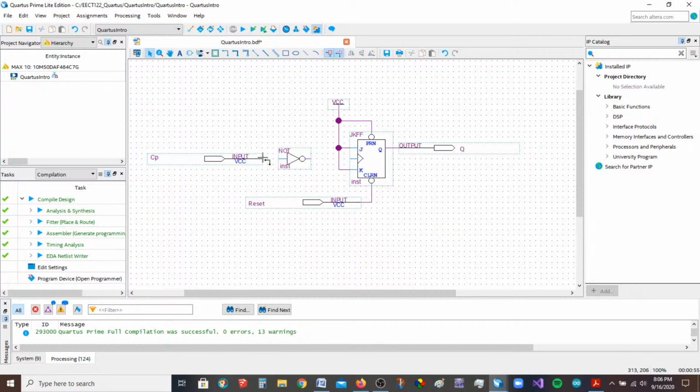Now I'm going to connect, click, drag, let go, click, drag, let go. And make sure you saw what happened there. If I do a Control Z, if I click and drag, it'll throw up a box like, "Oh, do you want to do something right here?" And I say, "No, keep going." Okay? With the previous versions of Quartus, if you didn't do that transition fast enough, it would connect in both places. But it seems like this version has gotten rid of that. So it's very hard to misconnect. So anyway, there we go.